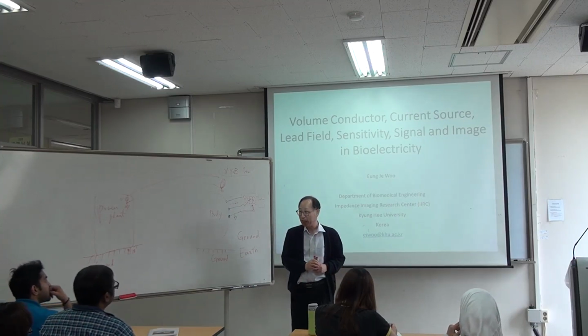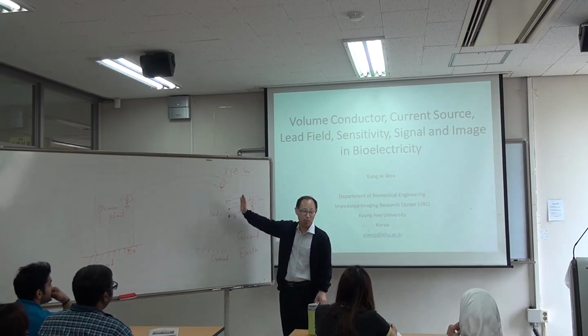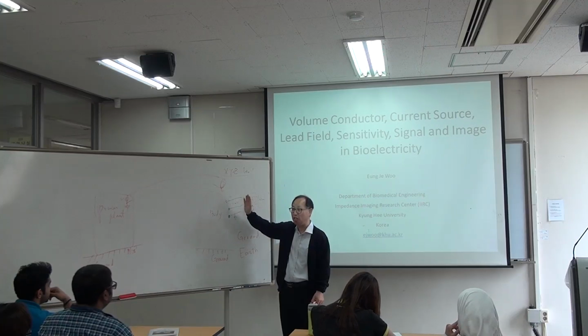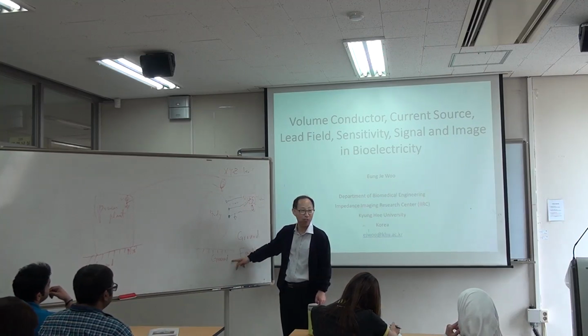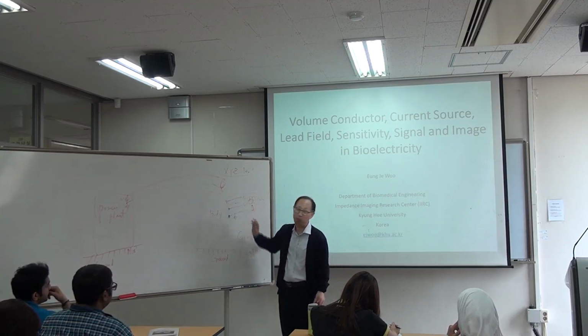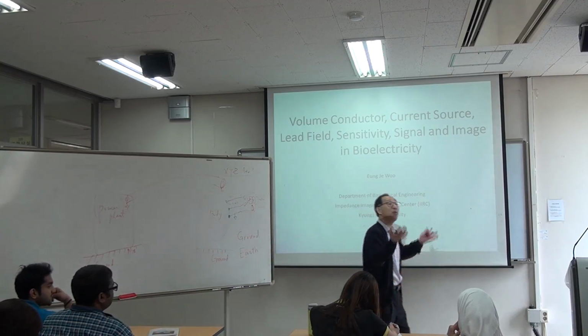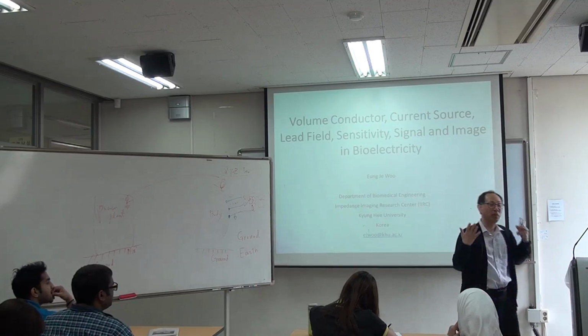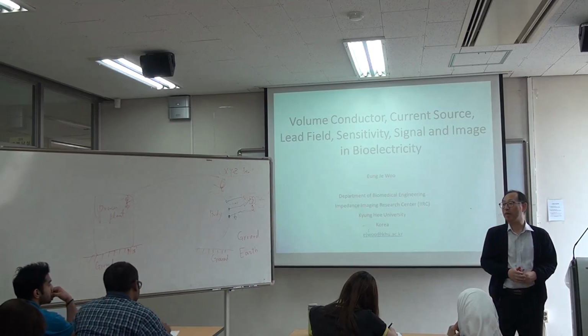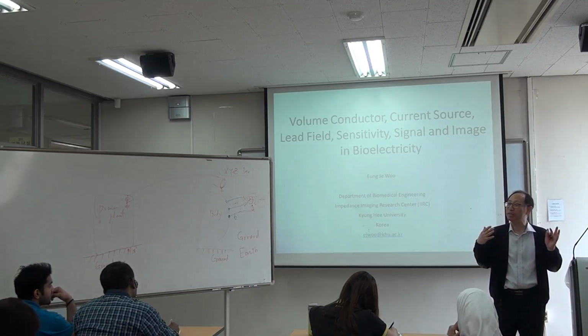But in mobile devices or in many medical devices, we do not connect the circuit reference point to the ground. They are separated. So this kind of device is called an isolated device or floating device. All mobile devices are floating devices.